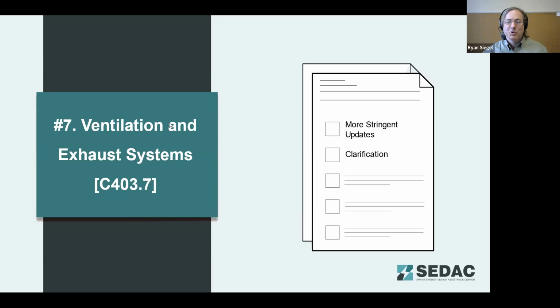These were definitely a little more tricky. Reading articles on the VRF systems, the intent is that you don't have an economizer because the VRFs have that 3-pipe heat recovery system built in. If you don't have that, you should technically still get benefit from an economizer, but the energy code hasn't built that language into the code yet.